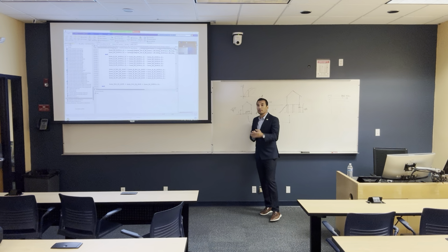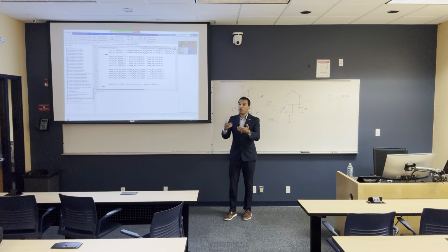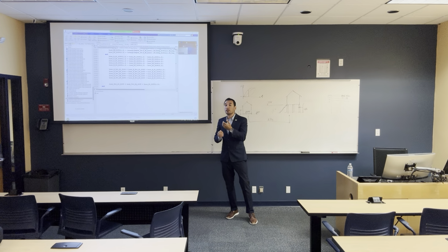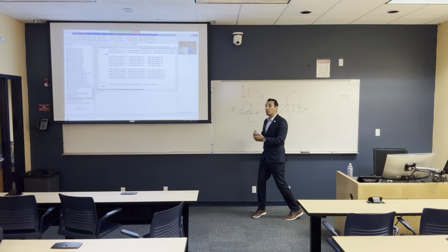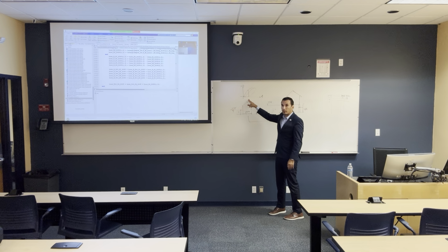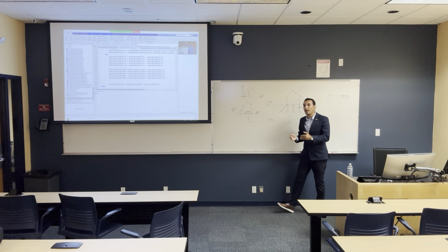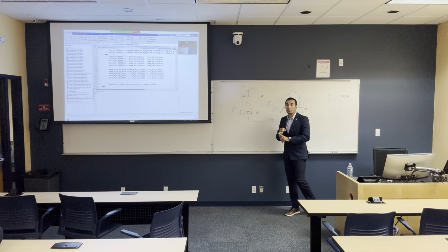Same thing with wind. When you improve the building, like put hurricane clips on the roof, using different kinds of measures, you play in the vulnerability. So you increase the resistance of the building. When you play in the building itself and improve it to have better resistance, we are playing in the fragility itself.